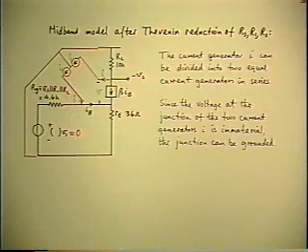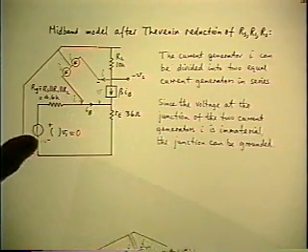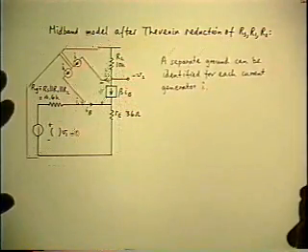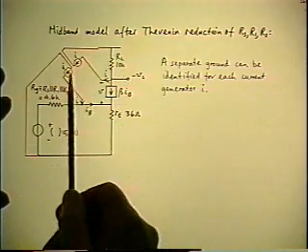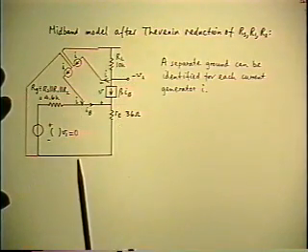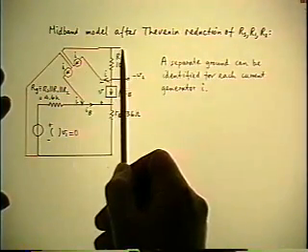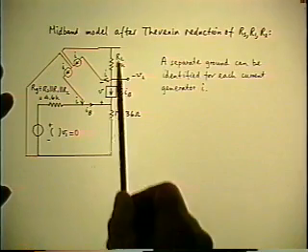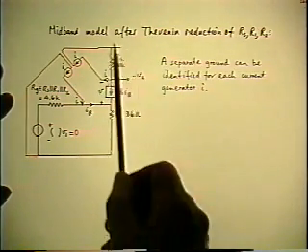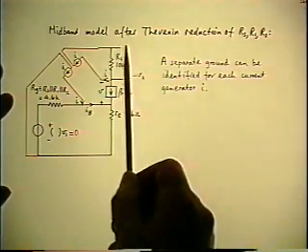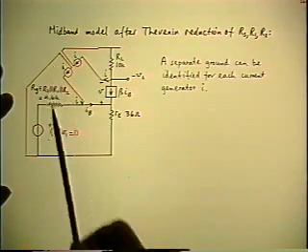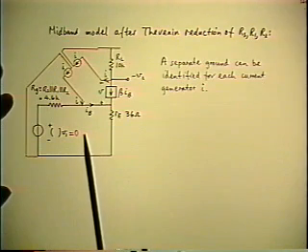But I can make a little change now. I can separate that connection into two different connections, one connected to the AC ground at the bottom, the other connected to AC ground at the top, and still nothing is any different, because remember, there's an implied AC ground connection from the supply to the bottom anyway. So the circuit still doesn't know anything different happened.